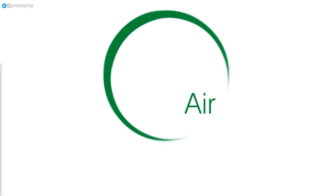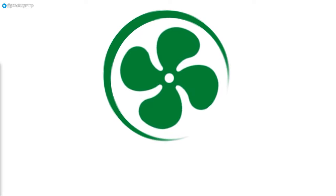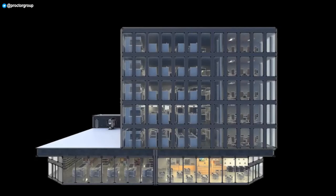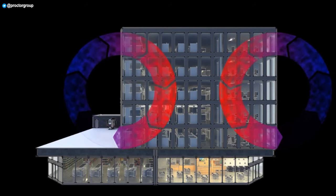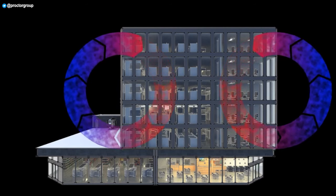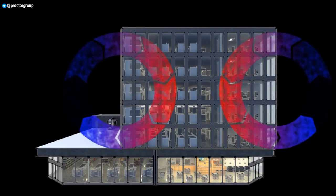It's important here to note that what we're talking about is unplanned air movement. Planned air movement, provided by ventilation systems, is an important part of maintaining good indoor air quality. So when we talk about air tightness, we really mean unintentional air openings and the uncontrolled exchange of air from outside to inside and vice versa. This can have a significant impact on the overall energy efficiency of a building, and as fabric insulation levels increase, this becomes an increasingly influential factor.